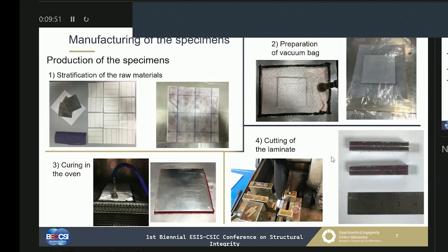So we took an aluminum plate as a mold, and we started with the sequence that I have presented: aluminum, composite, aluminum, composite, aluminum, with the adhesive at the interface. Every 3 layers of composite, we also operated a debulking step to eliminate the air bubbles entrapped in the prepreg.